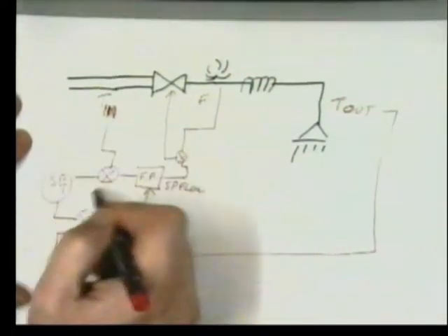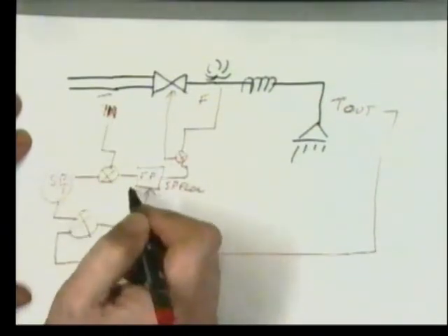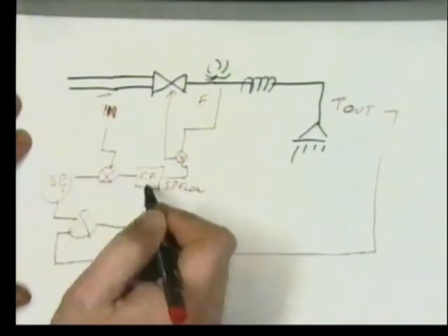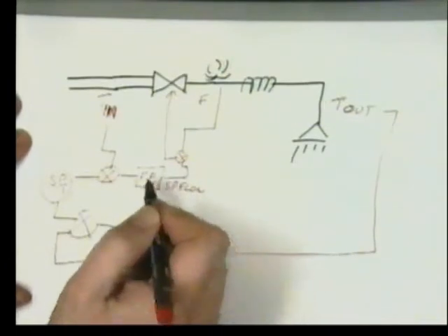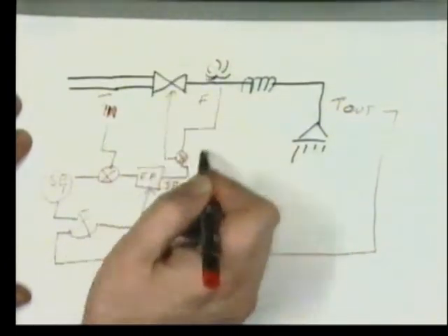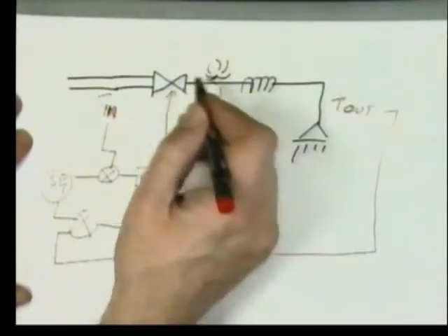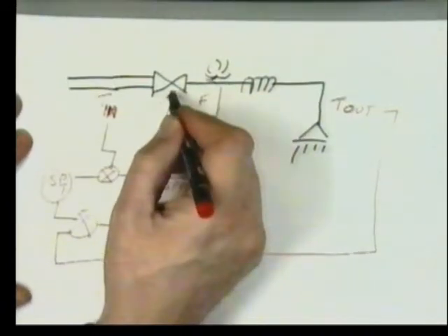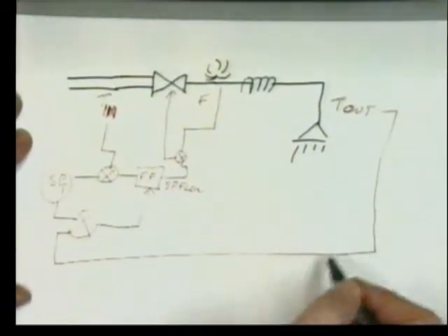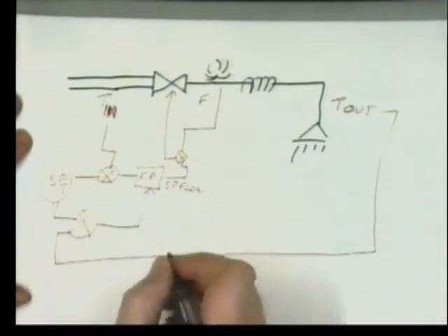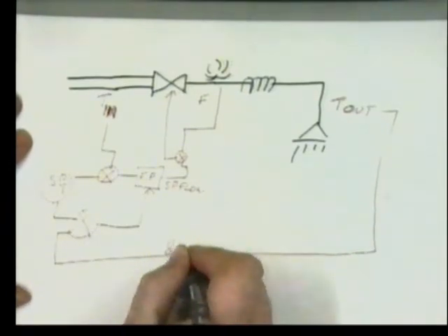A feed-forward loop for the input temperature that is predictive, that generates a flow rate. That flow rate is used for a feedback, PID, loop that controls the valve. And we monitor the long-term drift in a feedback manner over a long 8-hour period.